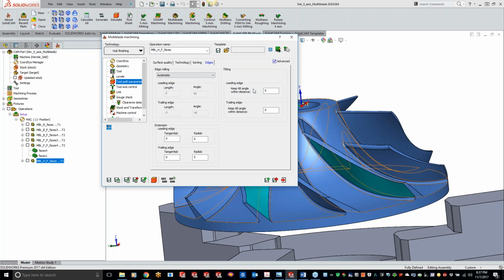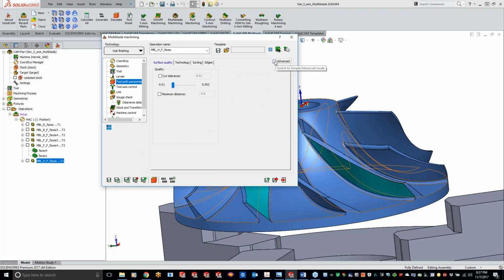To make things a little bit easier too, as you guys are getting started with this, turn off the advanced tab. That's going to simplify a lot of things. I always kind of forget about that. I know we went through the HSM and HSS. They all have that advanced. I always have that on, I'm so used to it because I need to see and know what's going on. But to simplify things for you guys, turn off that advanced, get the ball rolling, and that's going to eliminate a lot of the stuff you really don't need in there. But if you do need it, it's right there for us.